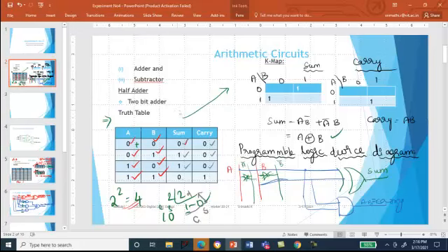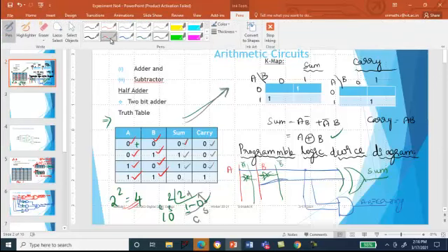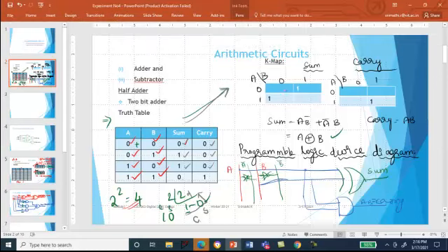For implementing the logic circuit, we will go ahead with the K-map. Since you have only 2 bits, you have 4 possible input combinations. So the K-map has A, B, 0, 1, 0, 1. In that, fill the table. What are the min terms? Here 0 0 is M0, this is M1, 1 0 is M2 and this is M3.